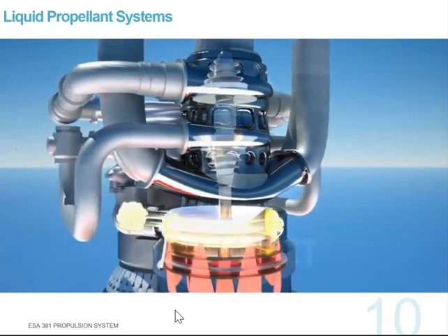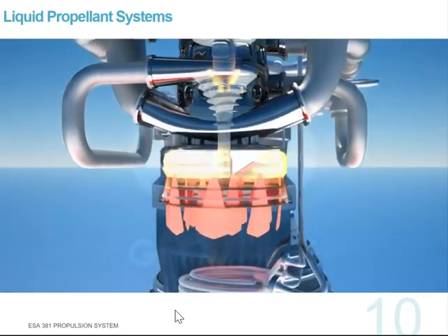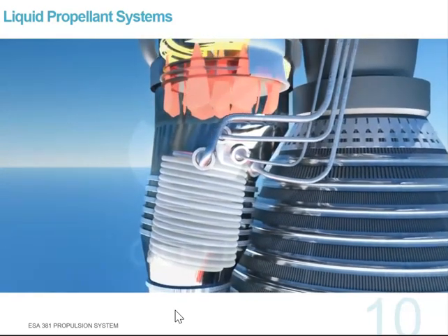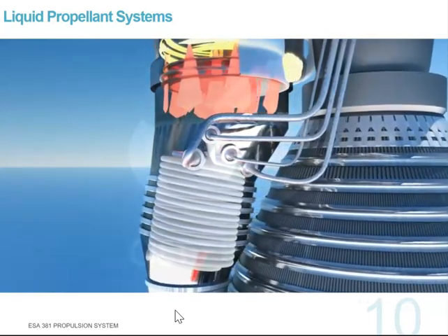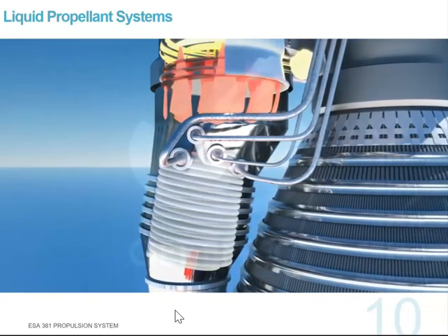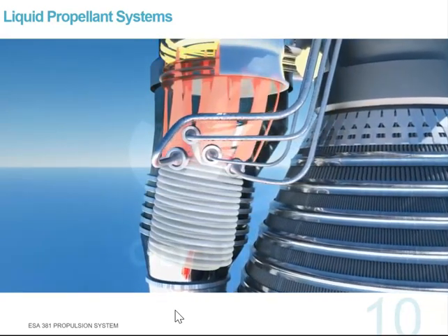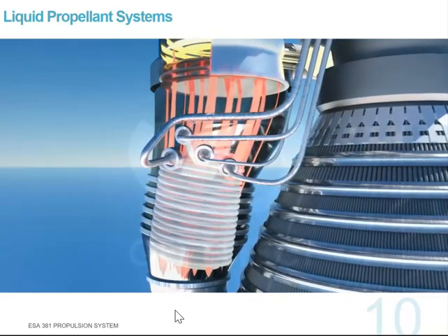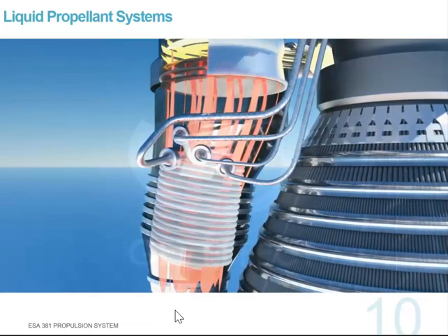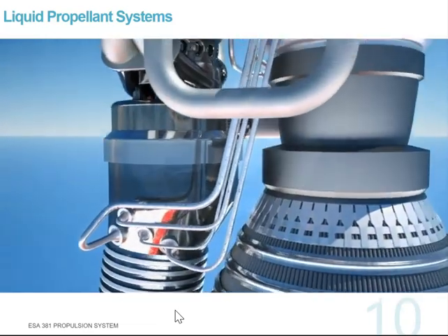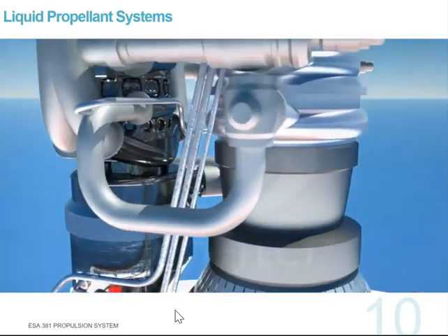To ensure proper suction at the pump inlets, a dedicated high-pressure helium system was used to pressurize the propellant tank, and high-pressure gaseous oxygen to pressurize the oxidizer tank. In the heat exchanger, the exhaust gases heated the helium coils, and phase changed the oxygen to gaseous in the oxygen coils. The higher pressure helium and gaseous oxygen then flowed on their independent pipelines, to pressurize the tanks.